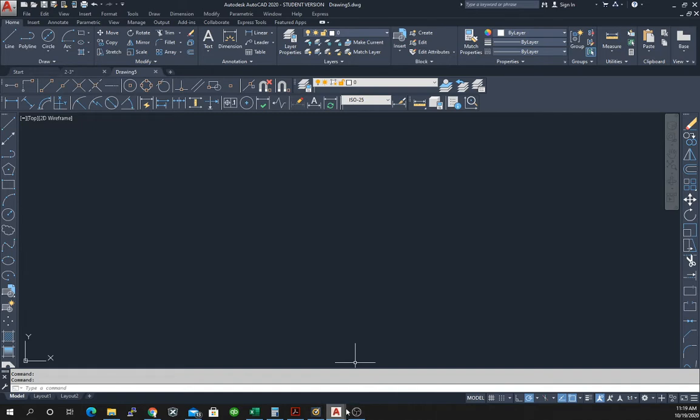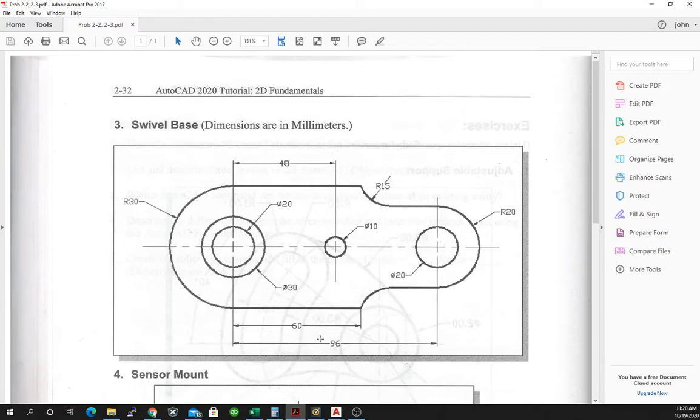So the first thing we're going to do is let's just draw that length of 60 line. We can start anywhere. Make a line of length 60. Come back to the drawing. Now, if this is a radius 30, we know directly above it is a radius 30. That means that 60 above it, we have this other line, which will also be a length of 60. So let's just do a copy.